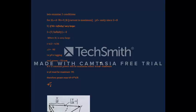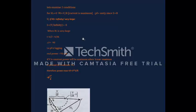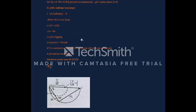Let's examine these two conditions. For inductive reactance X_L = 0, I = V/R, therefore current is maximum, and PF is unity since Z = R. If X_L is equal to infinity or very large, current is 0, as we can see. When X_L is very large, I = V/Z, which is equal to V/X_L. Therefore I lags by 90 degrees, so PF is lagging.